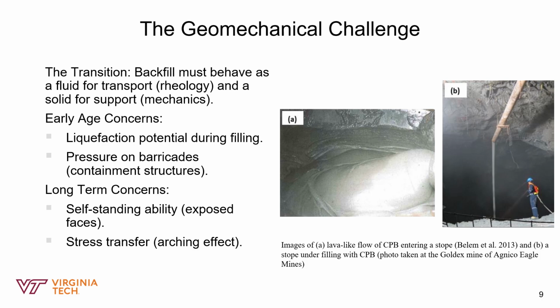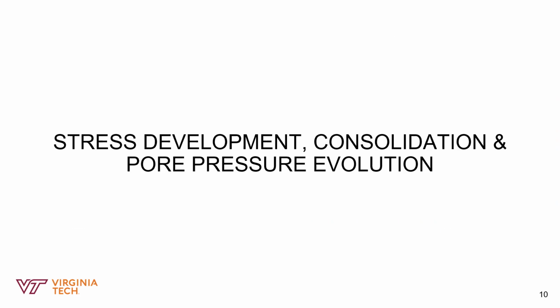We also need something we call stress transfer, or the arching effect, which we will also talk about in the next few slides. We want the fill to actively push back against the rock walls to keep the mine stable. In the next few slides, we will be talking about stress development, consolidation, and pore pressure evolution.